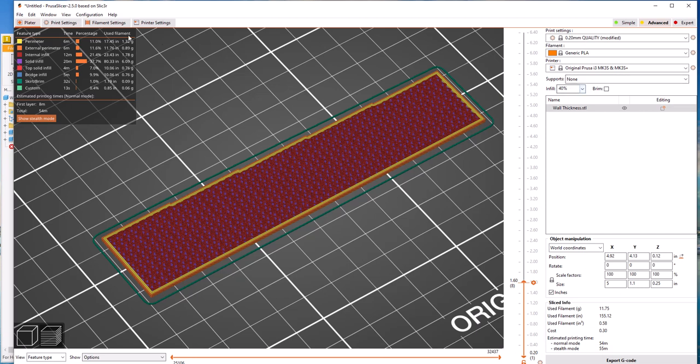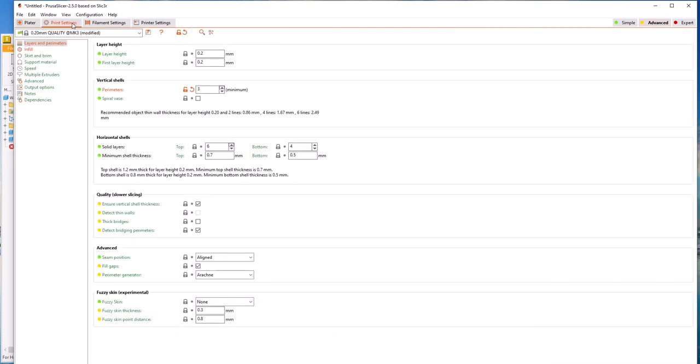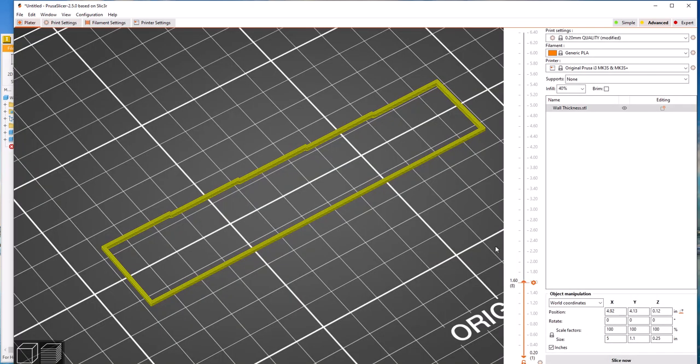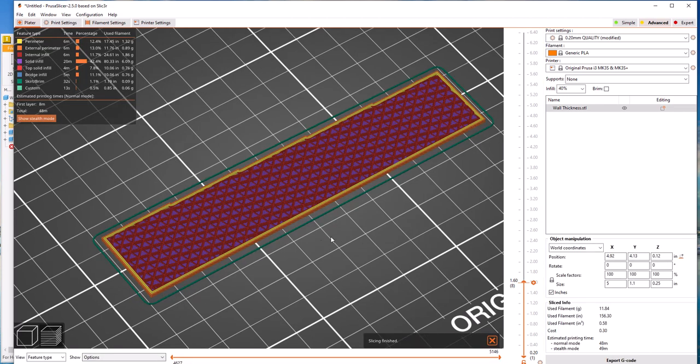So that's infill. We can come over here and change our infill pattern by choosing, instead of layers and perimeters, infill. And it's got the pattern right here. We can go instead of gyroid, we can choose any one of these. And we actually have examples of many of these different types in the back of the room by the 3D printer. So if you're wondering what cubic is, well, there's an example in the back of the room with various infill patterns. So go ahead and go look at that. Or we can just come here and hit slice, and there's cubic.